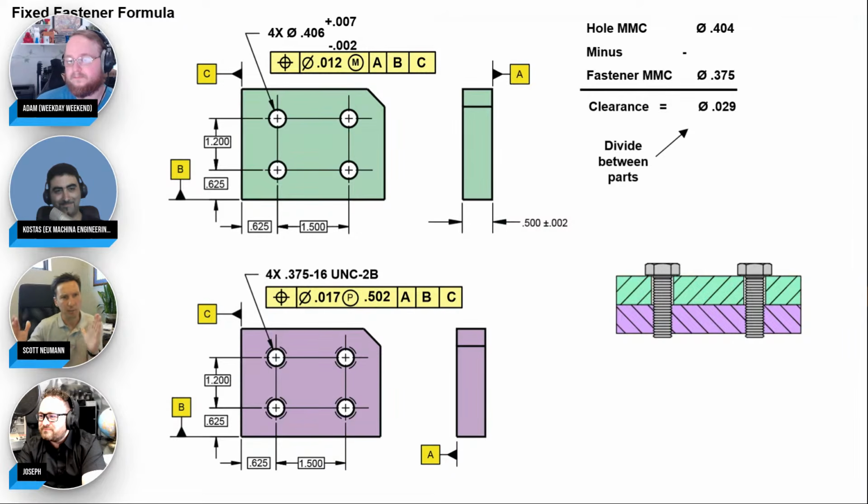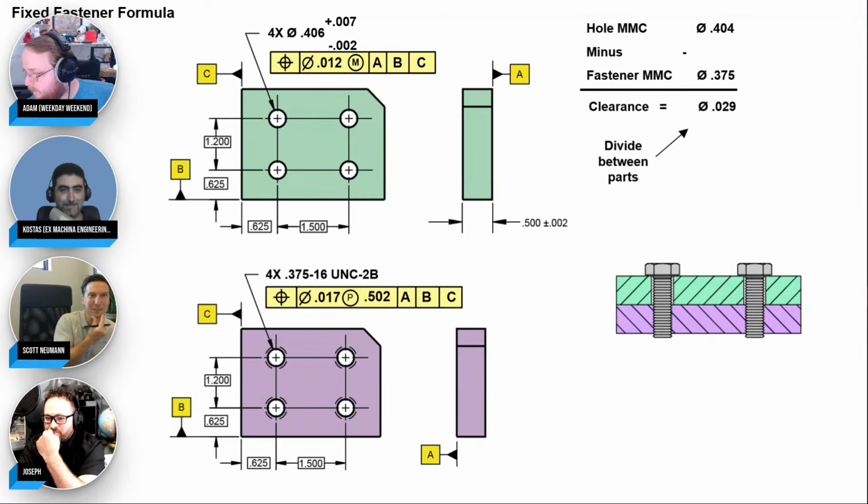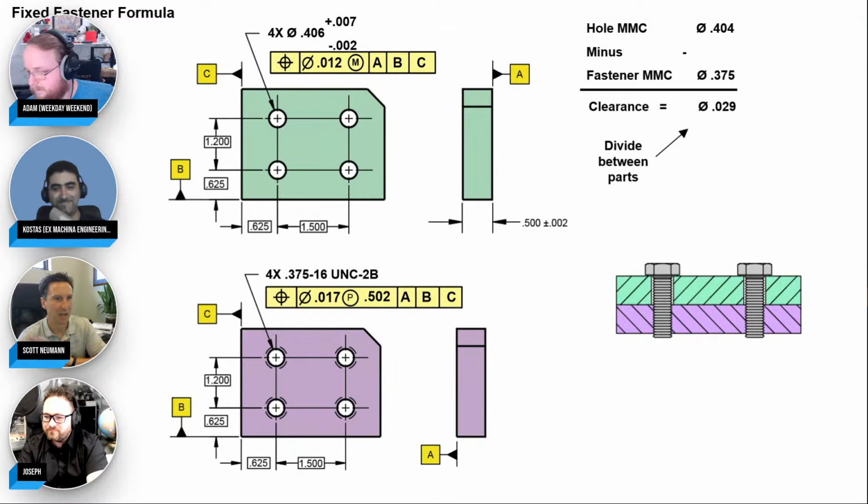Guard banding is where you artificially reduce the tolerance to protect your hard boundaries set by the drawing. So you're guard banding those tolerances, and cool, you do that for now. But then as soon as we get an upgraded CMM, then we're going to the full function. And then I don't have to go back to the design engineer and say, hey, can we get that 17 back on the function again? Sorry, that ship has sailed. We're back at 15. So yeah, I really like to stay functional, and then quality, yeah, you do your thing.